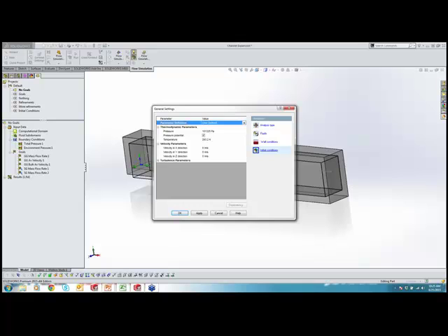The only thing that I'm having trouble with now is that I haven't come across a way to simulate the motion of the piston with this flow simulation tool. And the motion of the piston is going to be an incredibly hard thing to solve because that is a moving mesh boundary, which requires a transient solver that's also a geometry update.